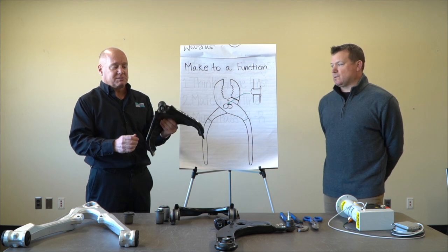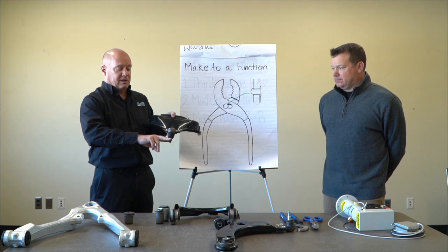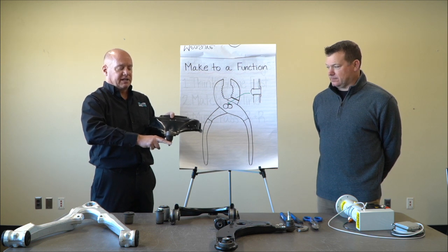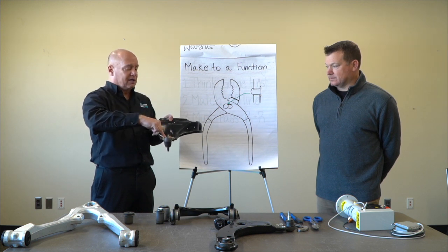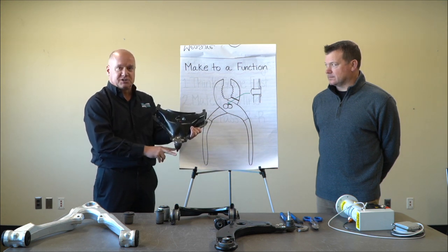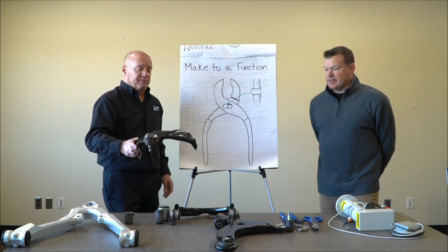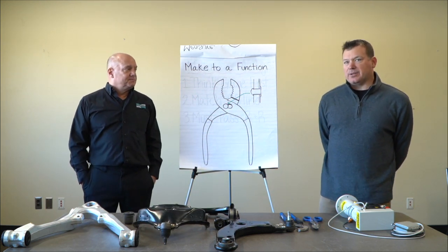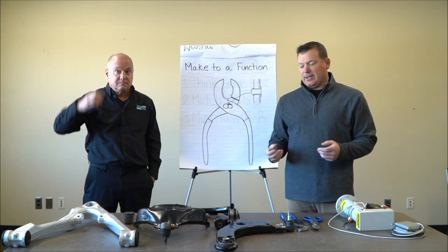Ball joints, which these control arms have, they have an articulation torque, and we'll have a torque unit rocking the ball joint, measuring that articulation torque as this is being roll formed, and we're controlling the actuation of the roll former. When the articulation torque reaches a certain torque, we know to stop, and then it's done. So the ball joint is another application where we use that. A lot of automotive components we do this with, like steering columns. In your steering column, when you make the adjustment, there's a hinge in there. It's the same idea there.